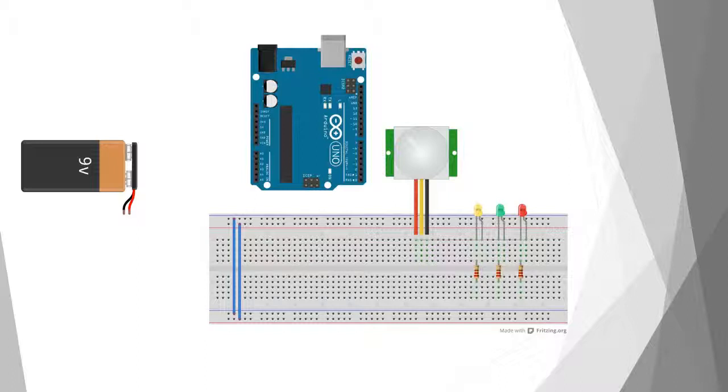First thing we're going to do, same as last time, we're going to hook up both ground sides and both positive voltage sides of the breadboard. These are the buses, so that we can use power and ground on either side of the board. It just makes it easier to put everything together.